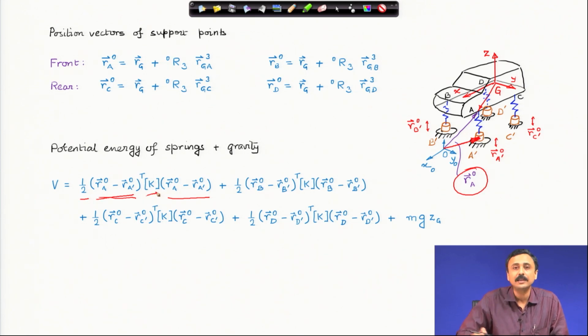In general, I have drawn it like a spring. It appears that it is one dimensional, but it need not be one dimensional. In that case, the stiffness would be a matrix. You can have stiffnesses in various directions. Therefore, this stiffness will have many components, because it will store potential energy if there is vertical displacement as well as horizontal displacement; then also you have the spring force.